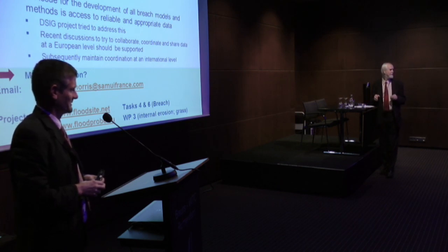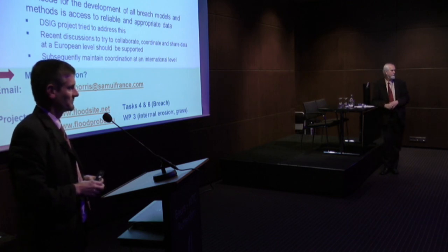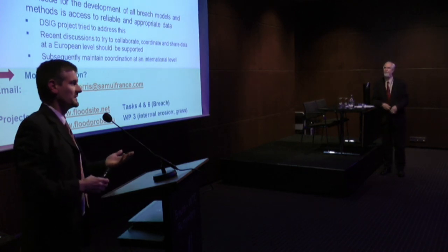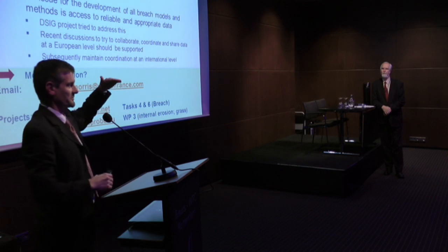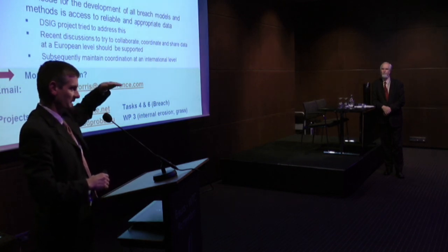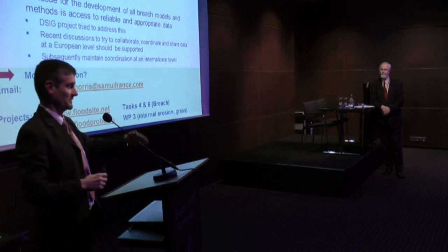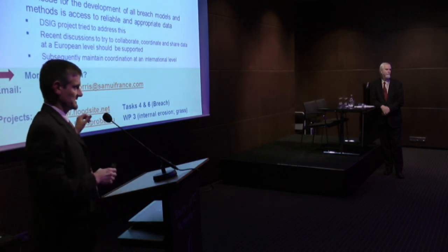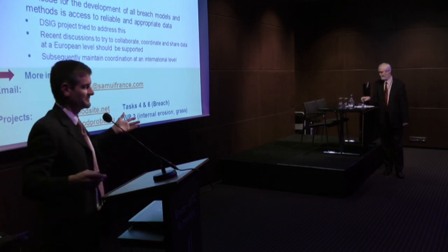It's more that if you have a small reservoir, you will have the same height, let's say the same water head, but the delta between time steps will be quicker. Yes, quicker, so then the rate of erosion will change as well. Yes, that's what I meant by stage volume. It's the rate at which that driving level will reduce as the flow volume goes through the breach. If you have a small reservoir, that will go down very quickly. So a small reservoir is likely to give you a flatter, less peaky hydrograph. Well, you might have a little peak, but then you've drained it.